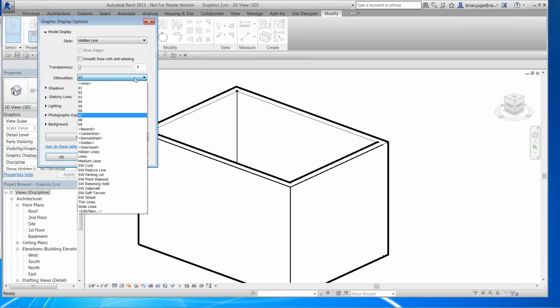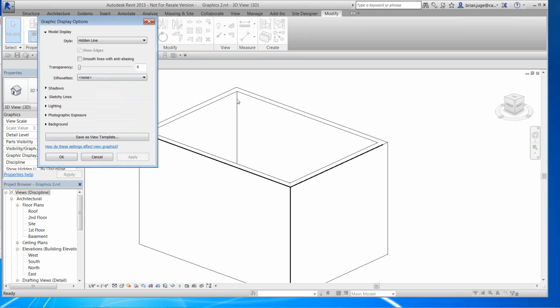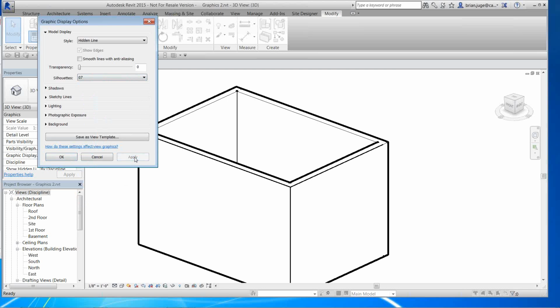So we use that. Now if I go back to none, hit apply, it goes back to the way it was originally shown. Okay, so we can change this out. Again, I'll go back to 7, hit apply, really pump that up, and give myself another thing. This has been such a great thing, and you do this in a couple minutes, and just print out regular drawings. You don't have to change any of the line weights. Just doing that alone will make your drawings stand out a lot better.